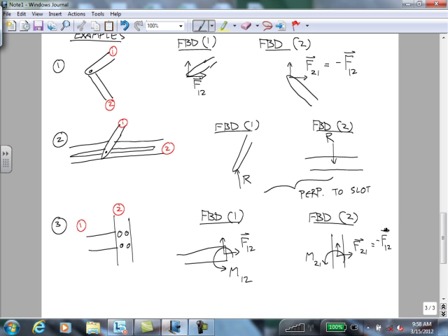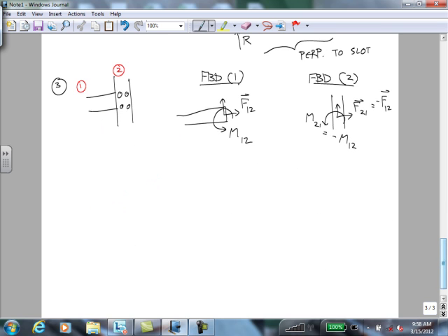Any questions about any of those? Okay, so this is the thing to remember. That's a lot of detailed information, but you don't need to remember that detailed information if you just sort of internalize this. The loads applied by a joint are determined by the motion that the joint doesn't allow.